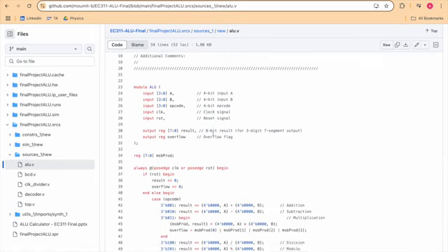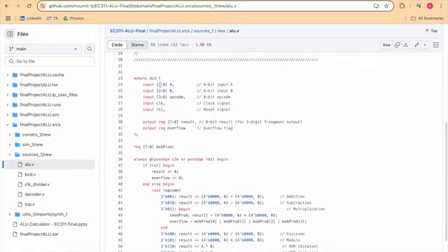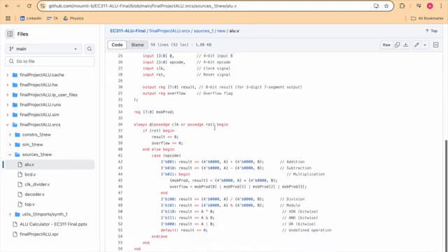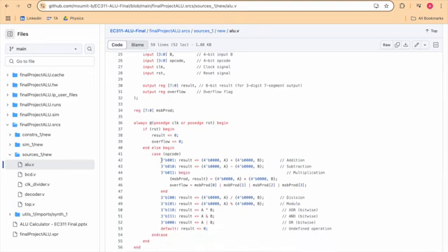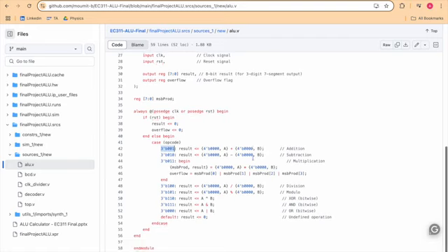So here in ALU.v, we can see how it takes two 4-bit inputs A and B and a 3-bit opcode to determine the operation. It also outputs an 8-bit result and a flag for overflow. For example, we can see here at 3'b001 how it's performing addition by adding A and B. Another example is where we can actually see the overflow, for multiplication, here at 3'b011.